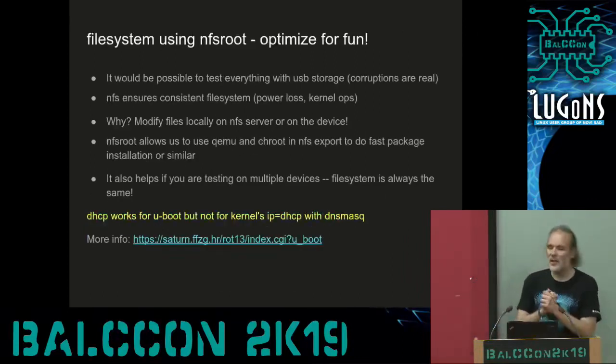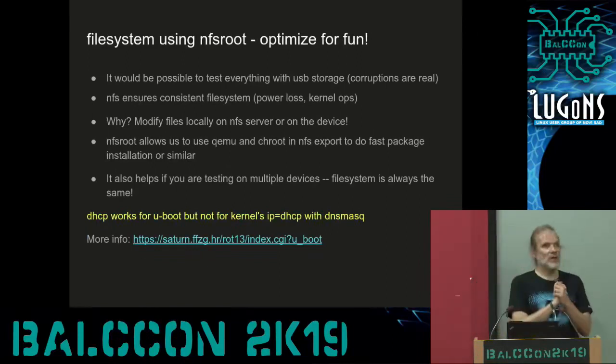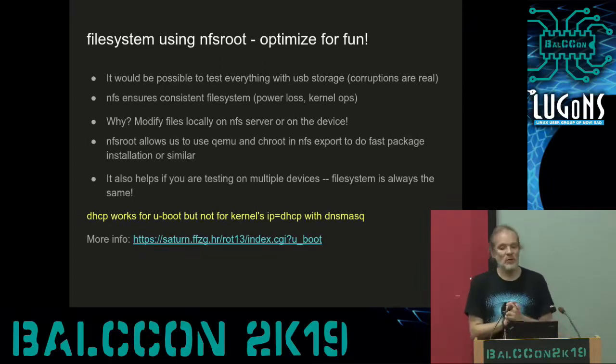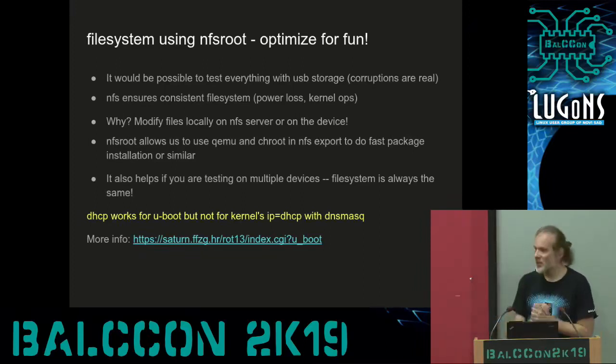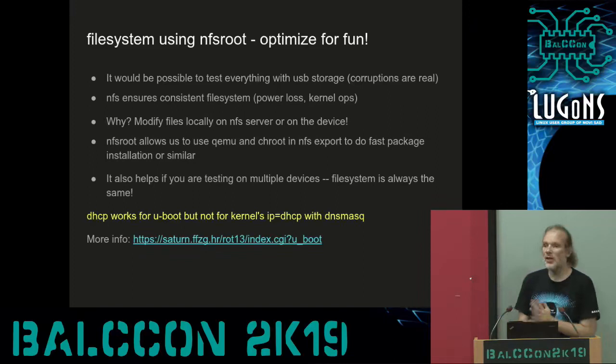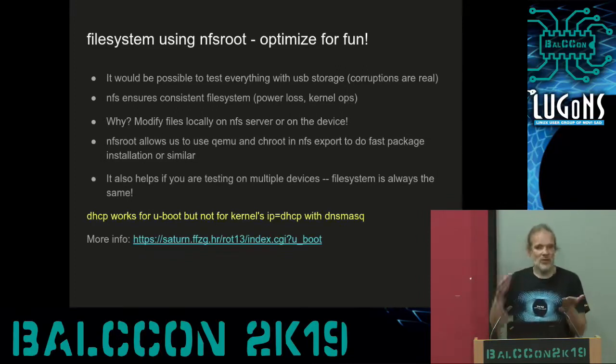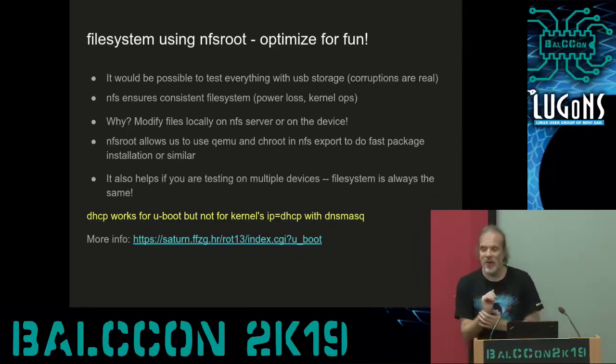In this process, I learned a valuable lesson. If you are developing something for an ARM board and you will compile the kernel multiple times, my suggestion is to actually set up NFS root. It will save you so much time, especially if you have multiple boards. For example, I used one board while the other was charging, and it was super simple to exchange it because all the data were on the NFS server itself.